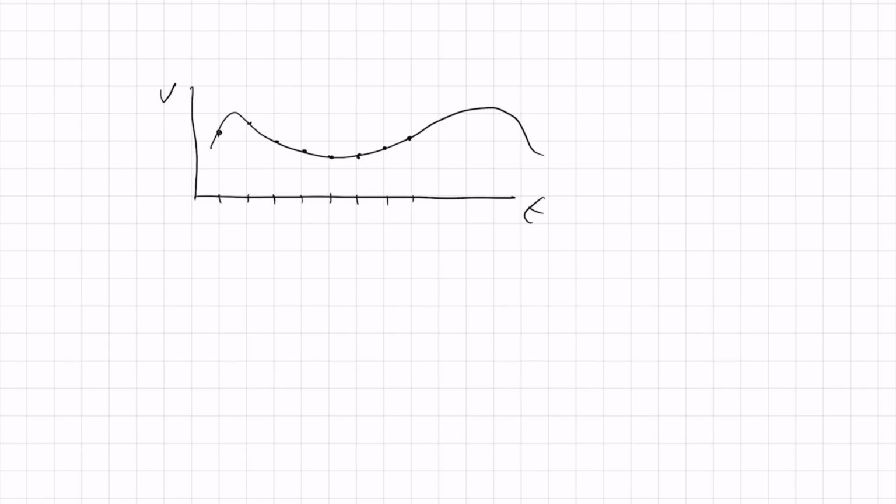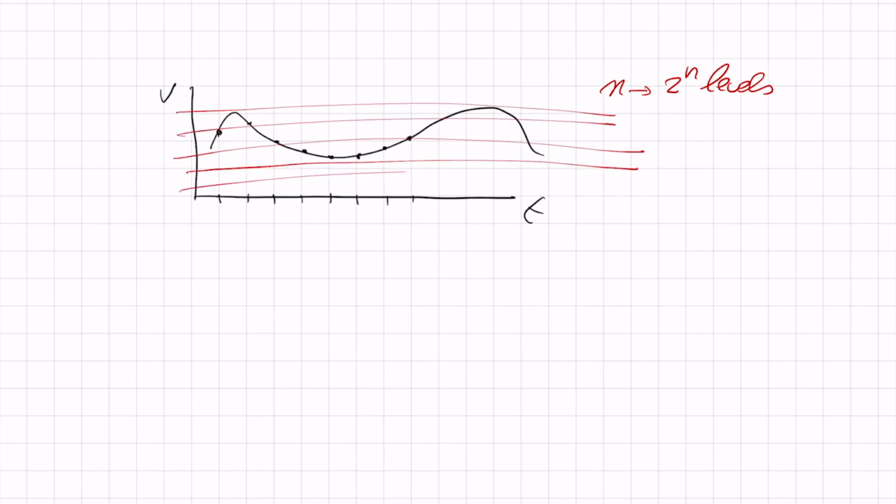But in a real A to D converter, we have levels, and we have n bits, then we have 2 to the power of n levels. And that means that the voltages that we store are just discrete values. They're not anything. So every time we take a sample, we take the nearest point that we have available, like this. And this way, those red dots are just a coarse approximation of my original signal.